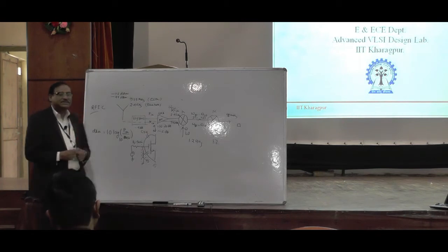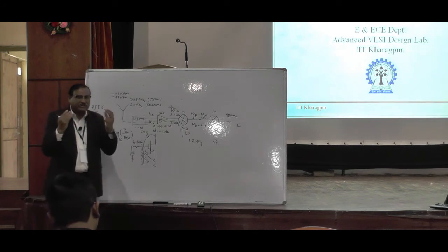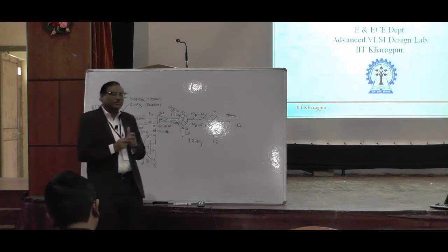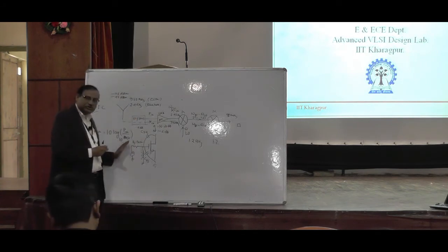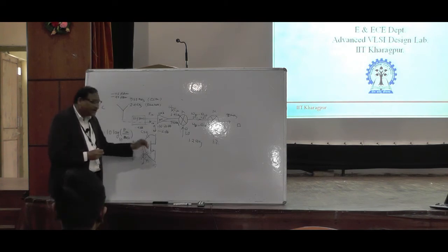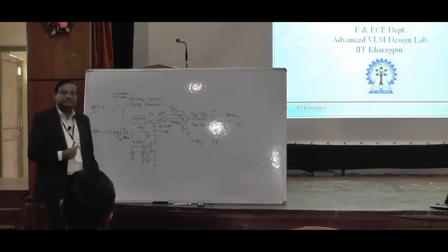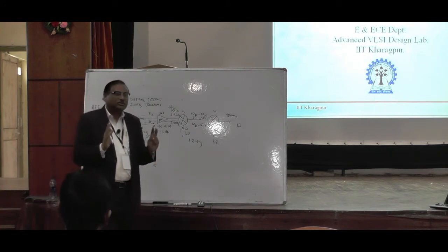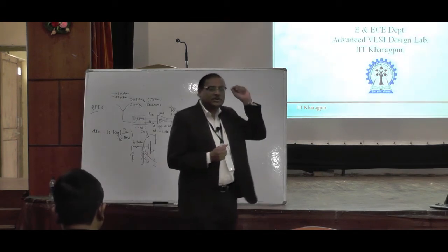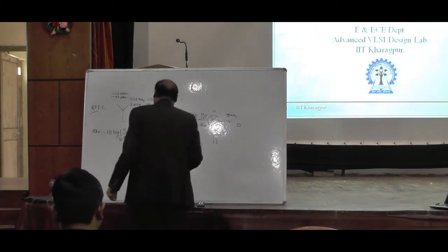And the inductor resistance would be 50 ohm. If you look logically, that 50 ohm will match with this 50 ohm source, and the reactive component of the inductor will negate the reactive component of the capacitance. So I require an inductor to terminate that source.